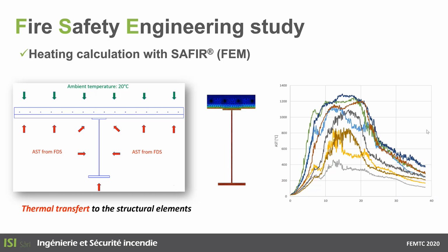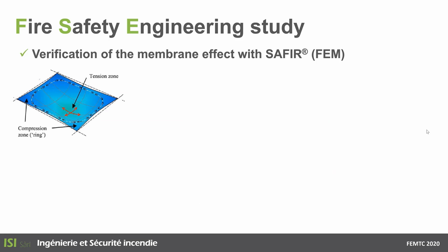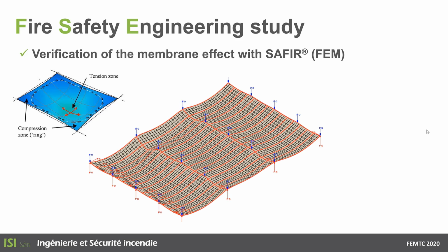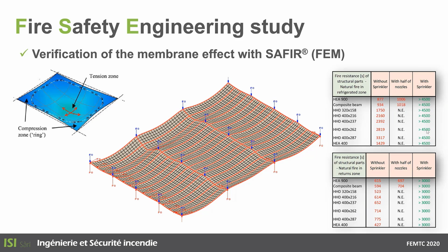To analyze the slab, we have to consider a bigger picture, so we modelized one portion of the slab with all its components, the continuous beam, the composite beam, and the slab with the rebar. With this analysis, in all cases, we did reach a resistance that is longer than the 30 minutes required, so the temperatures are taken for the full length of the fire duration and the slabs never collapse.